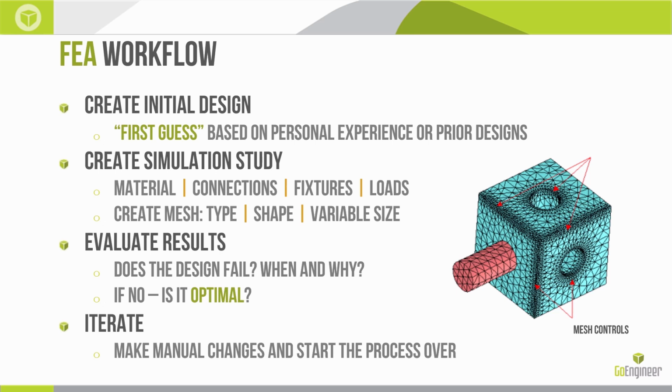What we are trying to look at is the results to check if there are any areas where maybe the part doesn't see any stress or strain. If there are areas of the part that are stress-free, then technically we might not need those areas in the model at all. But it's not a very automated way of optimizing the parts.